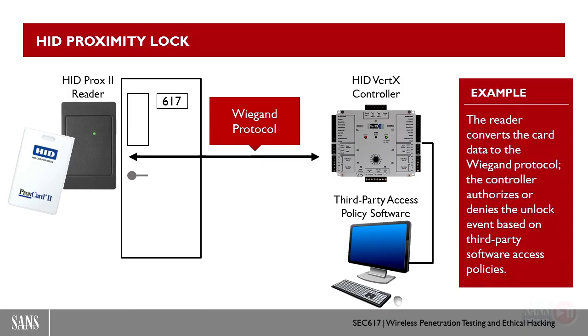And if the Wiegand reader requires 2 for Wiegand, 1 for ground, and 1 for power, you need a 4-strand cable to go to each of these readers. But if you want to do tamper detection, you need 5. So they price out a 4-strand cable and a 5-strand cable, and say the 4-strand cable is $1 a foot, and the 5-strand cable is $1.25 a foot.